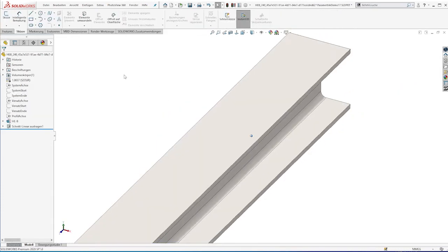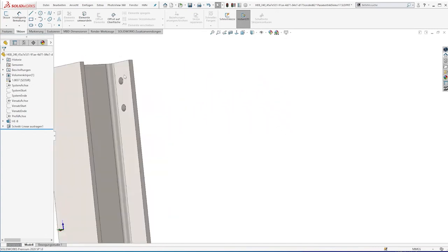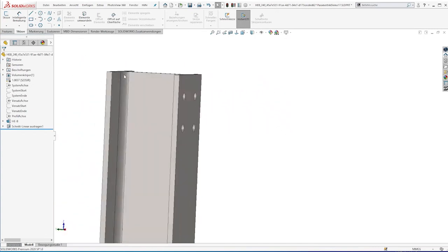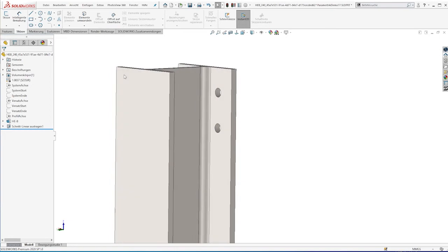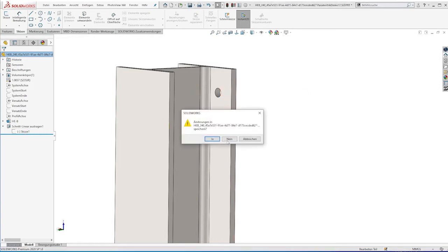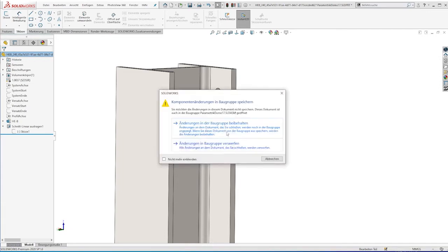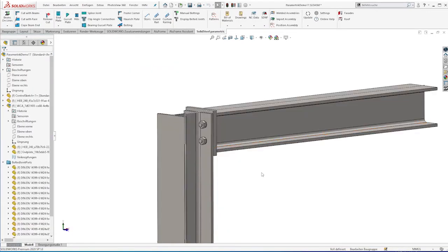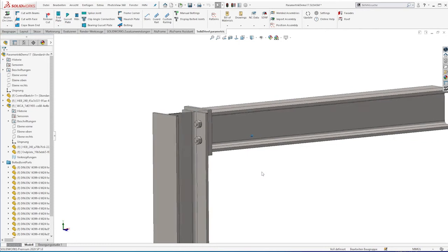We can also see that there are the bore holes, and it's not an assembly feature, it's a part feature, and it's a usual cut feature. And you can see there are no external references inside of this part, and that's the reason why we can keep the performance high even in larger assemblies. But don't worry, it's still parametric by 100%. We will see that later.